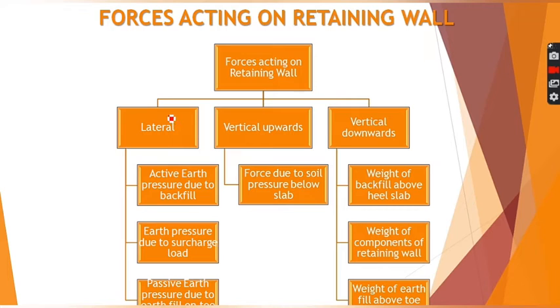This is the most important force on the basis of which the retaining walls are designed. Vertical upward and vertical downward forces are the consequent forces due to the provision of retaining walls. So the lateral force is the earth pressure,